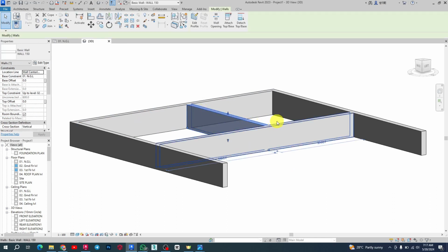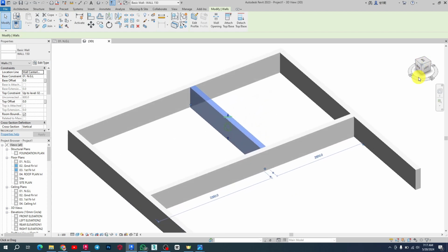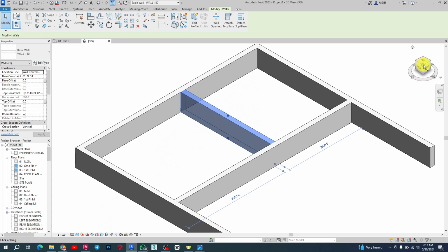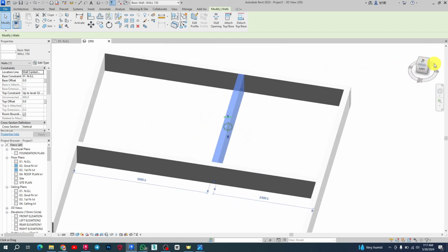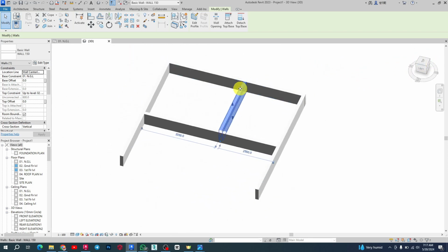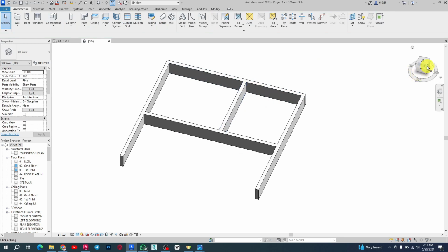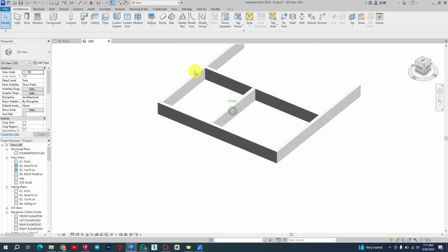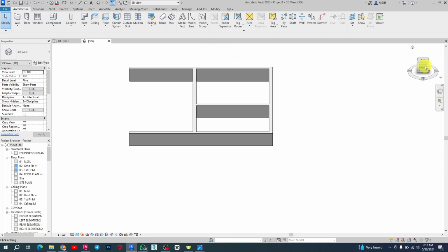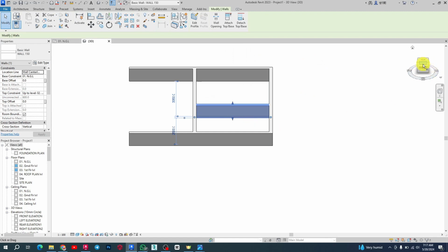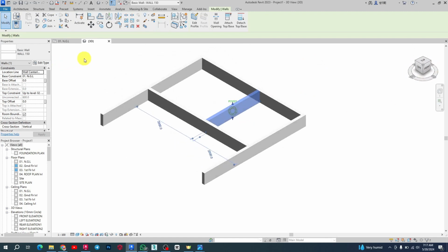So for you to rotate in Revit, you just click, and then probably you can use this cube here to rotate, right? You hold on this particular angle. When you hover over this one, you see click or drag. So when you click, you can rotate. Most often when you want to rotate around a particular point, you select the point. Like if I'm rotating now here, you see my pivot is centered around that point, but it can drift away from that point, especially if you have a very big project. So you always want to select a particular point or focus to orbit with.